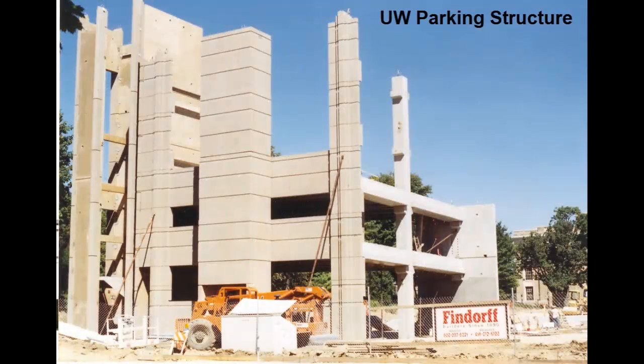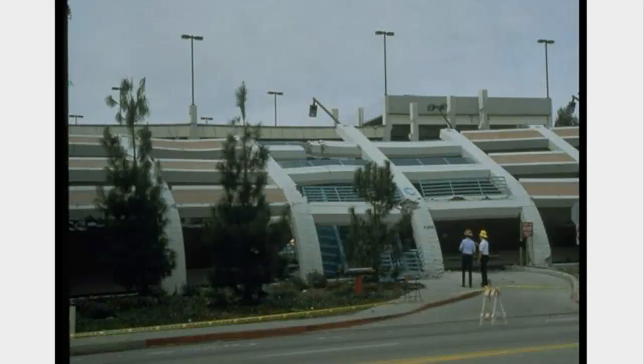This is less efficient, but preferred by architects for buildings where the diagonals of the braced frame would cross windows. This unbraced California frame was damaged in the Northridge earthquake. The cantilever columns were permanently bent sideways by the large earthquake forces. The simply supported beams were not damaged, however, but just moved sideways with the columns.